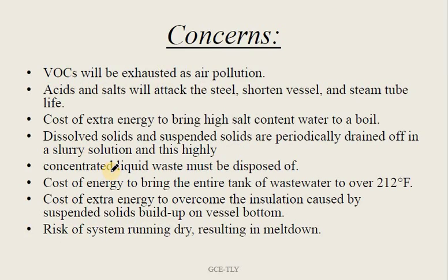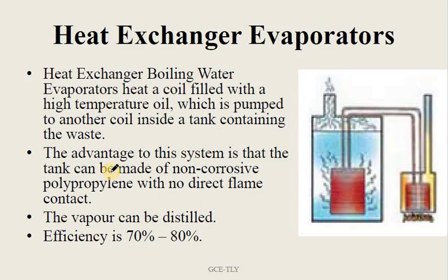And VOC is a problem here, the same acid salt problem is here, and the cost of extra energy for high salt content is there. Dissolved solids and suspended solids should be removed periodically. The same slurry disposal problem will also be here. And then the entire tank of water we need to raise to 212 degrees Fahrenheit, which is also an energy consuming process. Then here also there is a risk of the evaporator running dry and resulting in meltdown. So that's a problem.